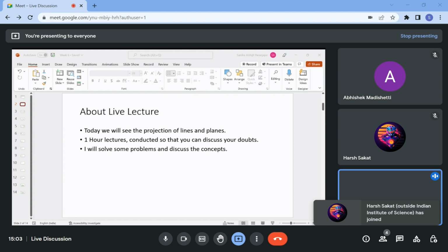Right now I was parallel to the vertical plane, so this was how the line was looking. So I had the angle with the horizontal plane which was visible in the vertical plane. This is 30. And my projection is looking like this in the horizontal plane. So when I start rotating, this point B is going to trace the circle, the yellow circle, and my angle with the vertical plane is going to change. So let us say I have rotated it from here to here.